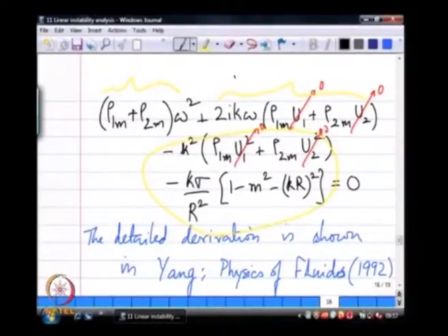So, if I go back, so that is the physical meaning of m and k. So, if I go back to this full 3-dimensional equation of a quiescent cylinder of liquid of radius r in a fluid of density rho 1 with the inside fluid being rho 2. This is essentially the surface tension part of the instability, that is the only part that matters, the densities do not matter. If you look at this red equation here, remember we simplified the previous more general equation by setting rho 2 equal to 0.